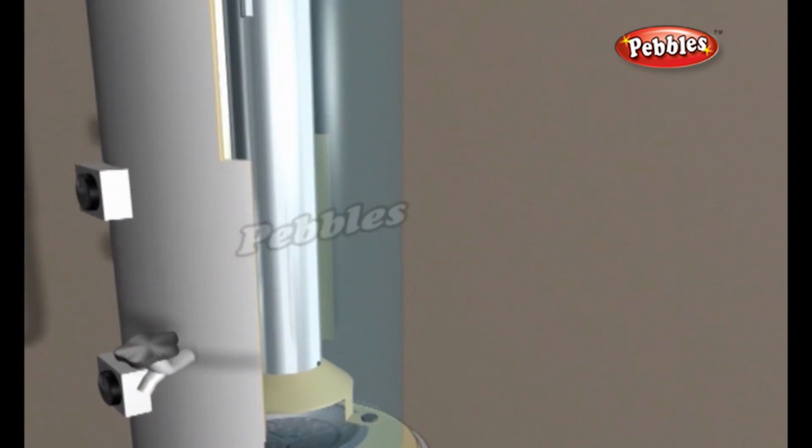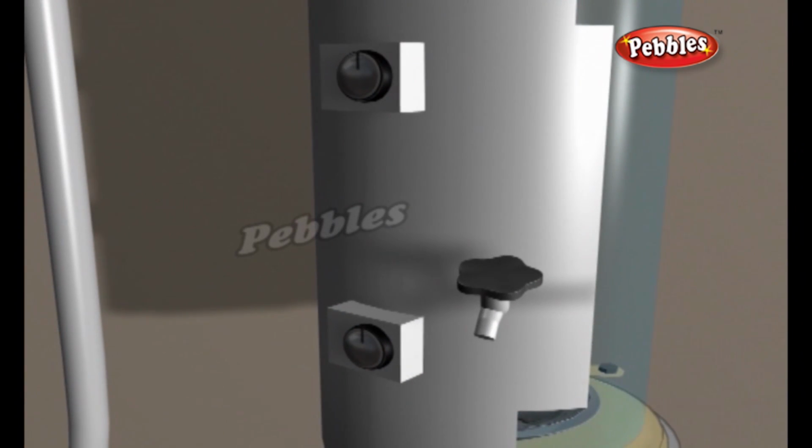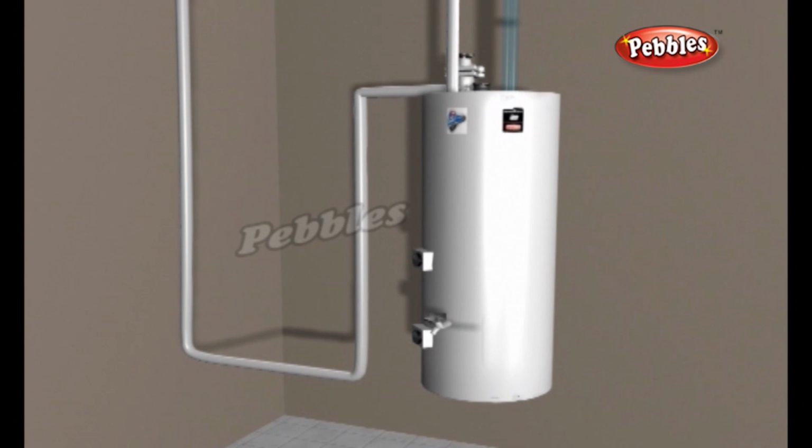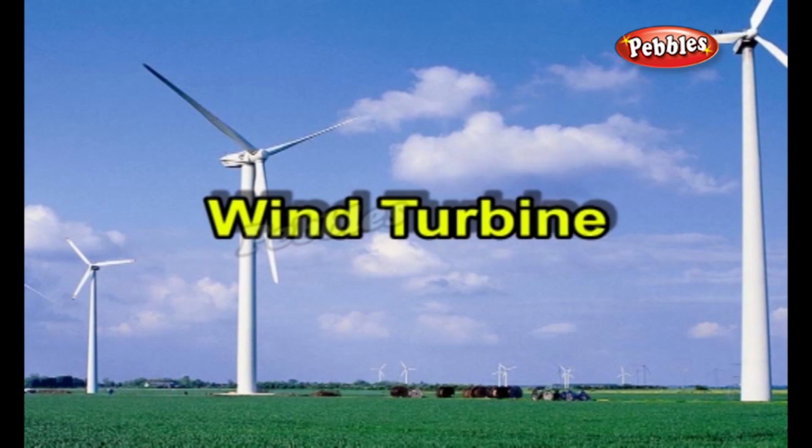The thermostat controls the temperature of the water inside the tank. Normally, you can set the temperature between 120 and 180 degrees Fahrenheit. It is generally recommended that you keep the temperatures between 120 to 140 degrees Fahrenheit, especially if there are children living in the house, to prevent scalding. It also saves energy.